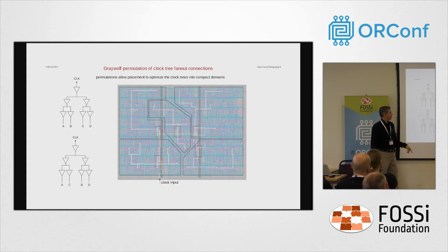The hard part here that I had to solve in the placement tool was that the ideal way to solve it is to try to cluster all of your terminal points of your clock. I had a sort of hacked way that didn't really work until I finally solved it in the placement algorithm, to tell the placement tool that certain points in your circuit are permutable. So that, for instance, for the clock domain, you may have a whole tree of buffers, but the clock terminals A, B, C, D are exactly the same behaviorally as A, C, B, D. Everything in detail about that is timing.